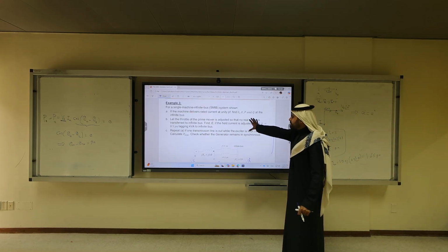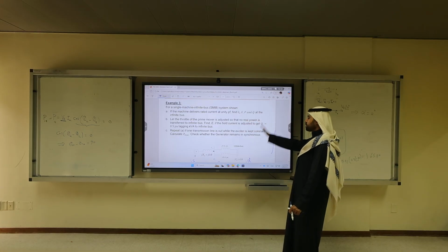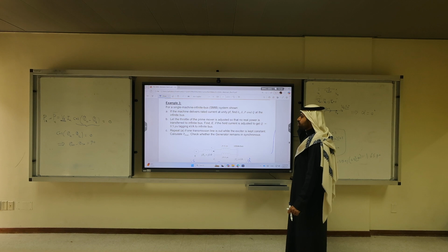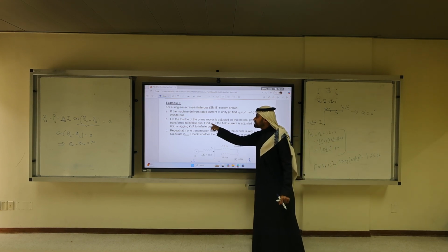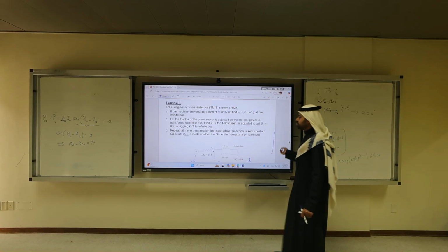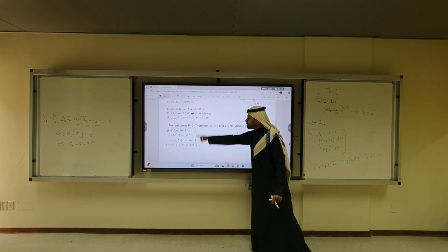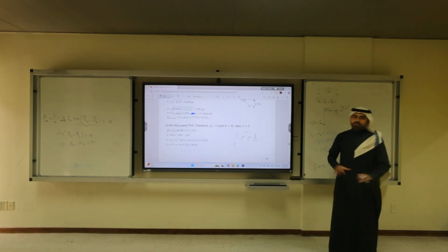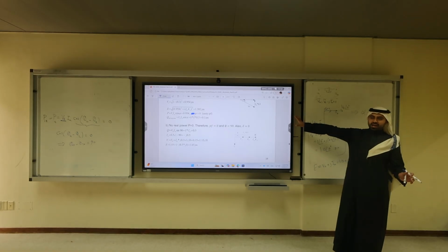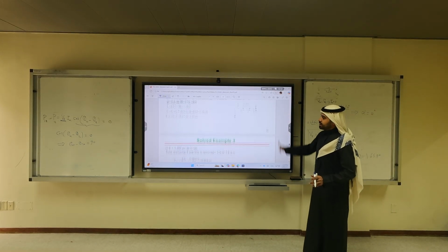What will happen here is that if the real power is blocked from going to the infinite bus, we are only supplying Q at 0.5 power factor. It means E will increase now. E will increase from the original value of 1.38 to 1.65. Okay? I'm trying my best to clarify these slides. It's not easy. This is high level.